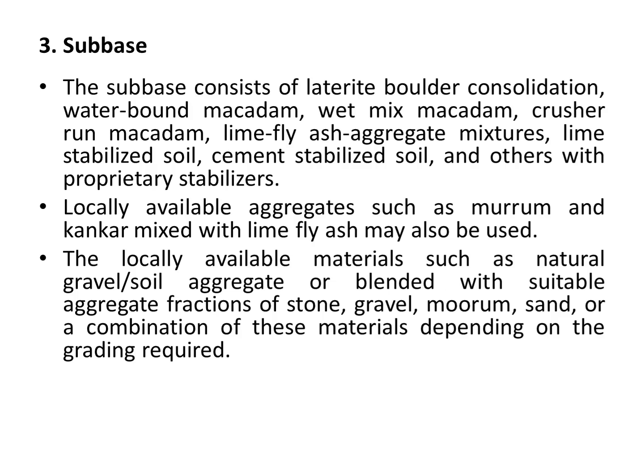The third component is subbase. The subbase consists of different types of materials such as laterite boulder consolidation, water-bound macadam, wet mix macadam, crusher run macadam, lime fly ash aggregate mixture, lime stabilized soil, cement stabilized soil and others with proper stabilizers.